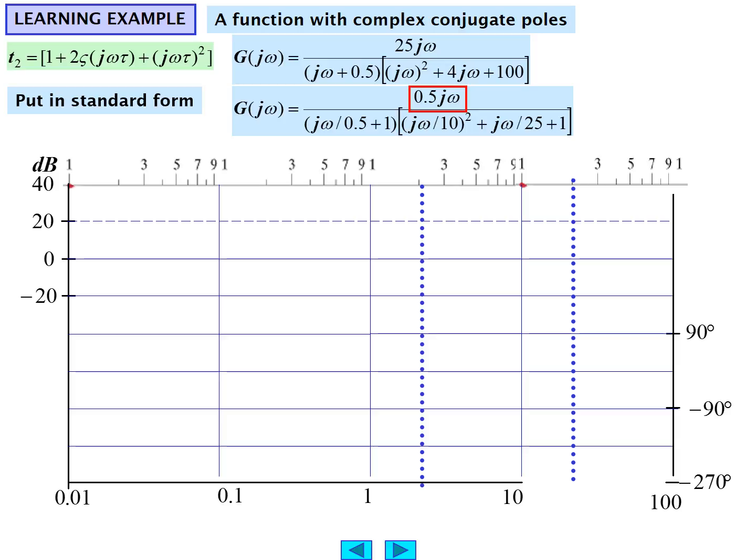We can pick the break frequencies appropriately, and the question is where does it get 0 dB? It gets 0 dB at omega equals 2. So there it is, 0 dB at omega equals 2. And at omega equals 20, it should be 20 dB greater. And of course, it's 0 dB at omega equals 2 because of the 0.5 cofactor that it has out front. So when omega equals 2, j2 times 0.5 is j1, and then the magnitude is 1, and 20 dB times log of 1 is 0. That's how that works.